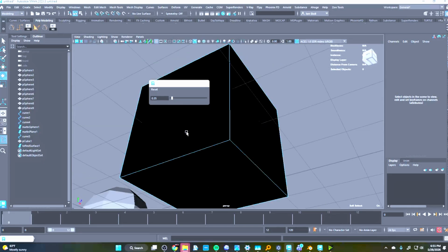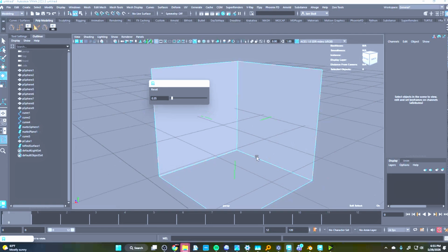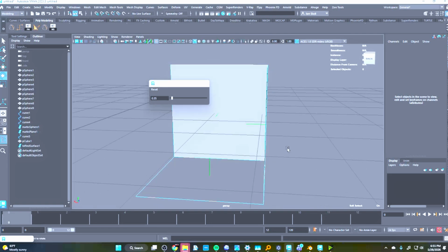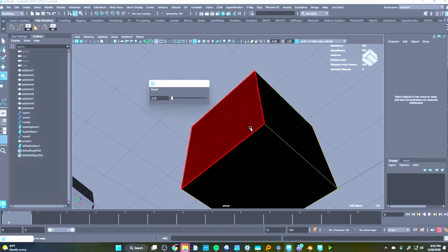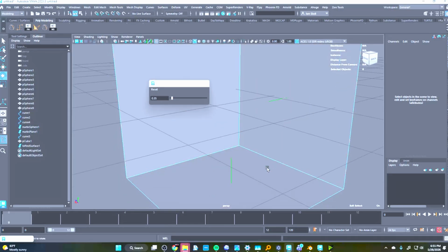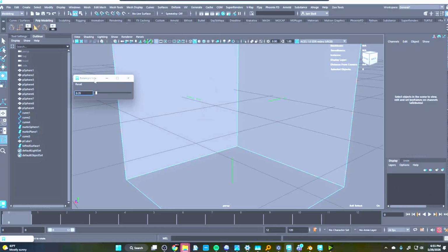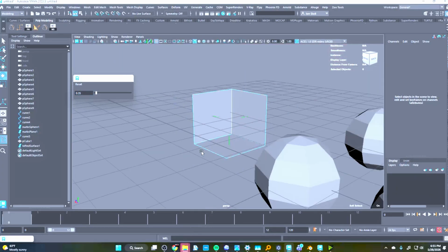So it'll actually render black like that. Some programs by default will render both sides, so it'll be double-sided. And some programs do not do that. So that's very important. The normal facing is a very key thing.